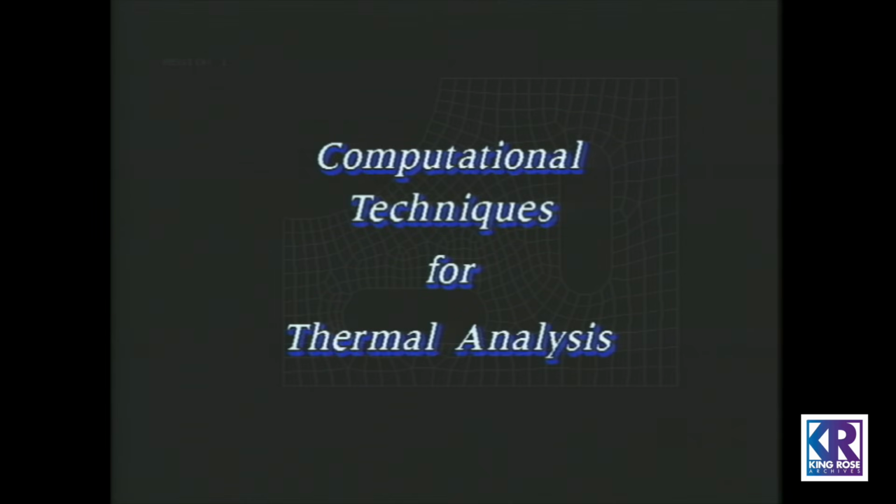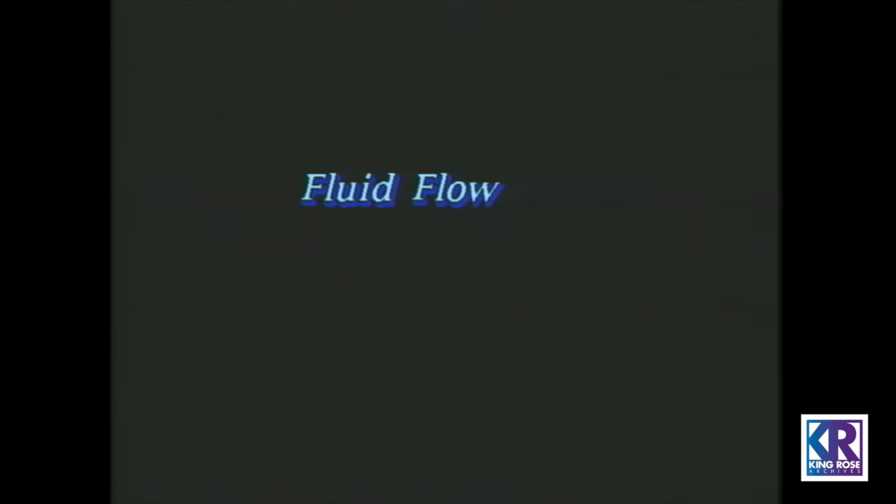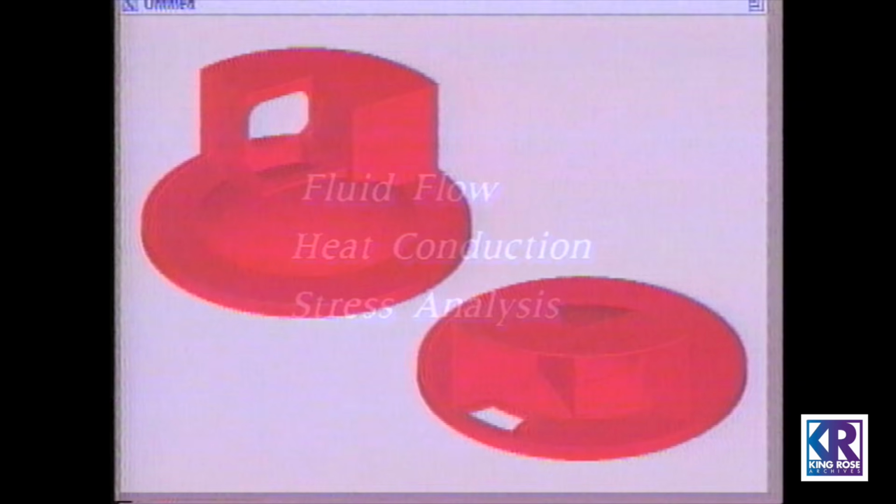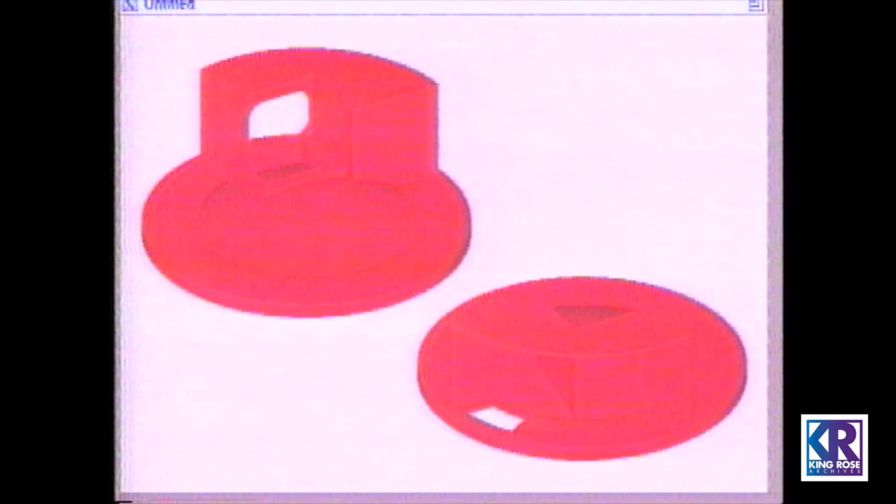Once the mesh has been created, the design may be analyzed to predict fluid flow into the mold, heat conduction as it cools, and stress analysis as the metal contracts. An example of cooling by thermal conduction of a mold will be shown. Different colors represent different temperature ranges as the casting cools.